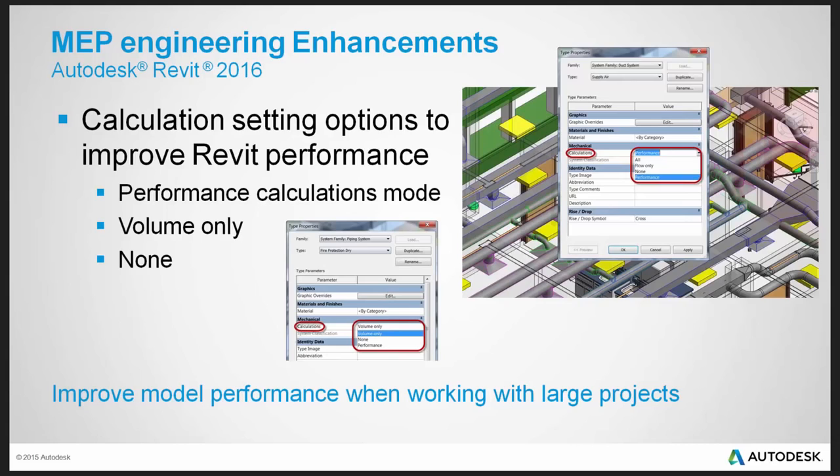is something that you might set for your fire protection, your vent, other classification systems where you don't need friction loss and all you might need is volume. There is still an option for none, but any upgraded project will have the calculations parameter set to volume only for existing projects in which the calculations parameter was set to none.